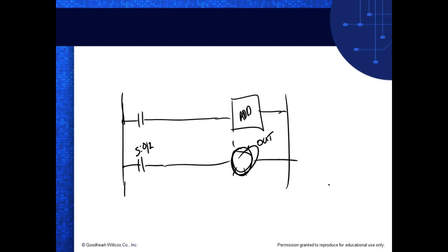I'll do a program with more than one add. How is that status? Well, it's going to be according to the last add instruction you did. So if you want the status of this first add instruction, then by George, you better check it after that add instruction. And then you would check it after the next one. Understand? You just can't add 15 numbers together and then examine the status bit down here, right? Well, I want the status bit for this first add. Well, it's going to give you the status of the what? The last add.